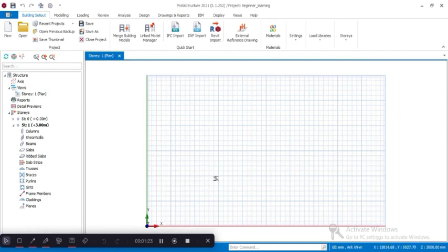Then drag from left to right to create a rectangular box. When you release your mouse button, all entities completely contained within the box will be selected. But when you drag from right to left, and the rectangular box contains all the entities within the boundaries, and across the boundaries, they will all be selected. So anyone you touch, just remember to touch. So we've seen all those things there. Then if you right click the selected entities, you'll see the pop out context menu, which allows you to edit and perform other tasks related to that entity.